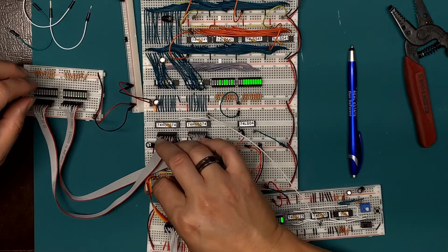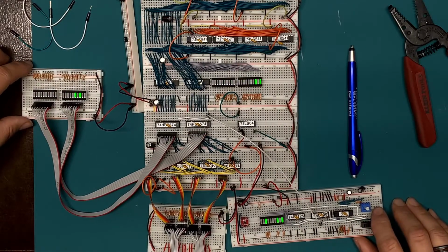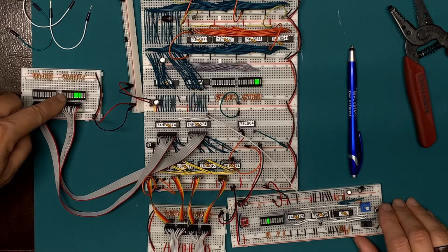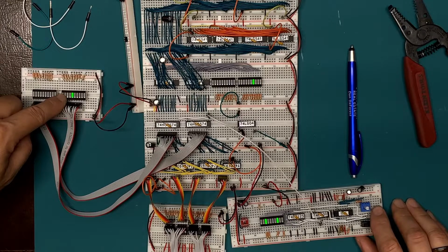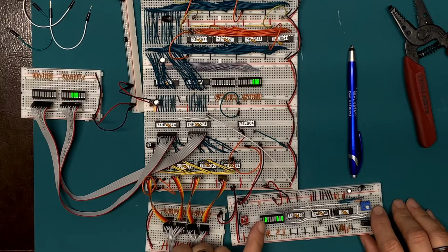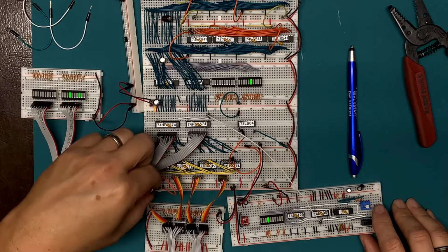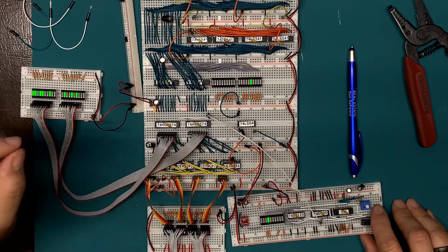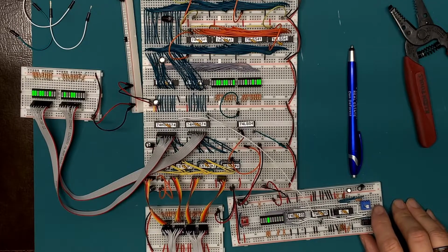Such that when I clear it, so when I press down, I'm latching. When I release, I'm incrementing. Press down to latch, release to increment. So the high clock to latch and the low clock to increment. Now the problem is the parallel load. Maybe that will work.